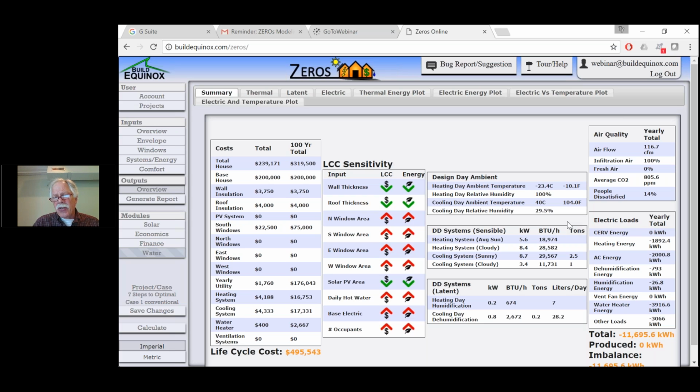So if we had an average sunny day, the heating load would drop by, say, about 5%. But on a cloudy day or at night, windows detract from thermal mass. They make your house, when it's excessively windowed, drop like a rock in temperature when it's not sunny out. We see that we go up significantly from about 5.9 kilowatts to about 8.5 kilowatts of heating.